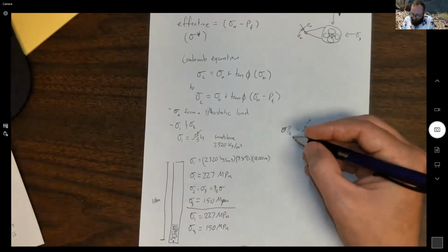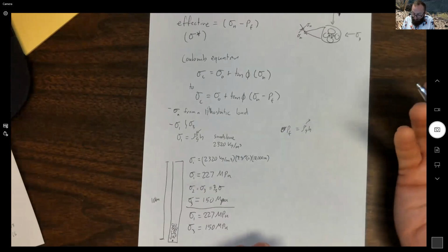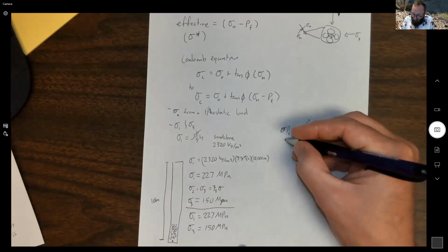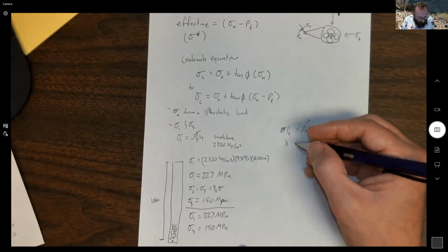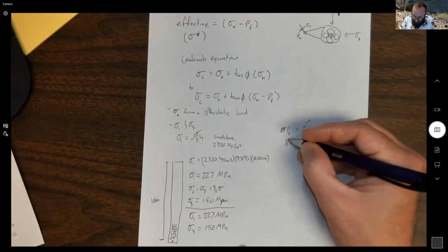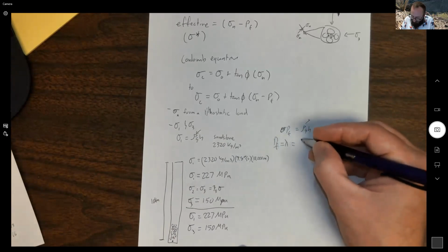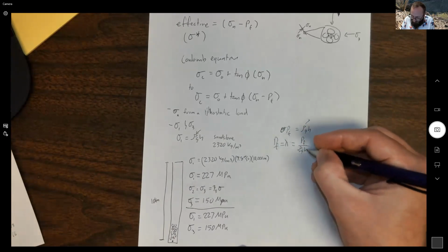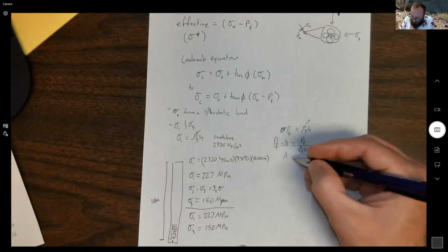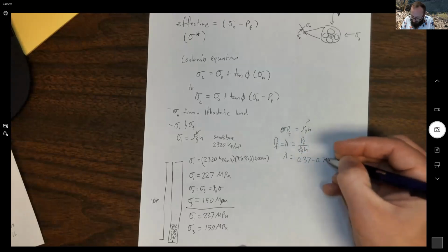Also, it turns out that normal pore fluid pressures that are measured in boreholes are usually a ratio. So we're going to say pore fluid pressure is usually a ratio of our rock rho gh, and for typical places in the crust, it's about 0.37 to 0.47, but it can get more elevated than that.